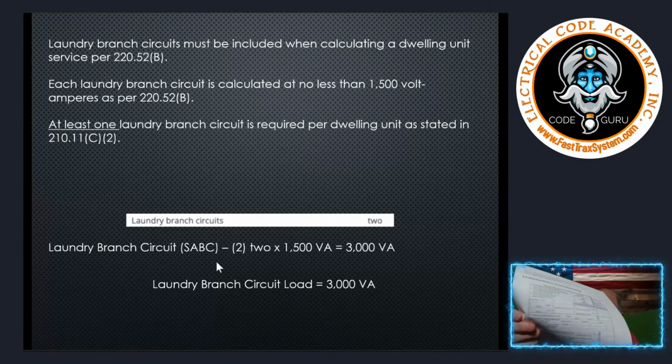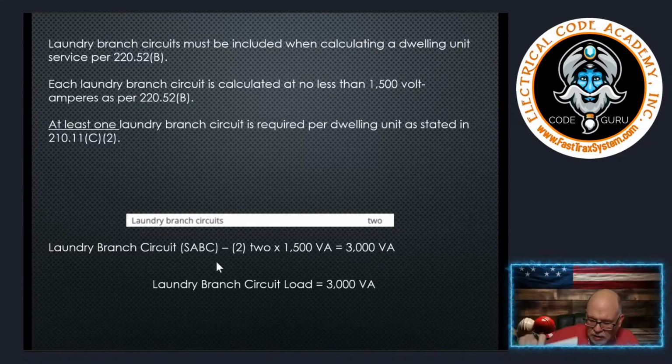I know y'all can't see that, but I just wanted you to see that we're working through the form. The reason for this form is it also gives you code references, so at any time you're stuck, you can always look at the code references and they'll send you where you need to go. I also should remind you, if you're in the middle of an exam and you get stumped on anything, go to the informative Annex D of the NEC. It gives you examples of a single family dwelling calculation, so it gets you back on track.